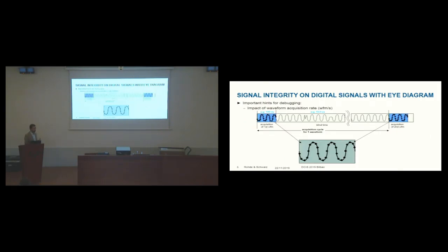In the end, the oscilloscope or the acquisition tool will take a very long acquisition, and then it will post-process this acquisition by software during a long time. During this long time, we will have a blind time. The measurement tool or the oscilloscope will see nothing. And then we'll get a result.